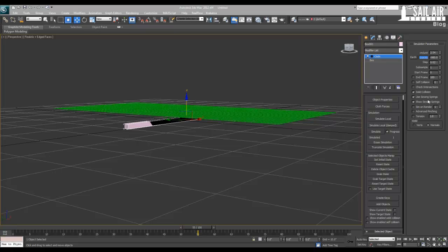Okay, step. It's the minimum size of time step the simulation takes. So right now, each simulation step is done in 0.02 of a second. It must be less than the length of one frame. So what this does is it steps through each bit of the frame. It goes 0.02 seconds forward, simulates something, 0.02 seconds forward, simulates the next frame, etc. You only see each 30th of a second, which would be 0.033 of a second, but it automatically does it in 0.02. We'll change this around to get a better simulation at the end.